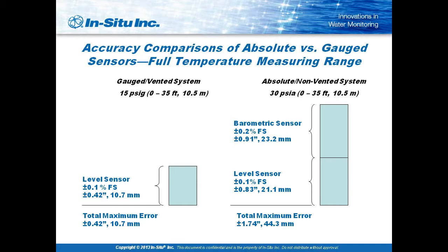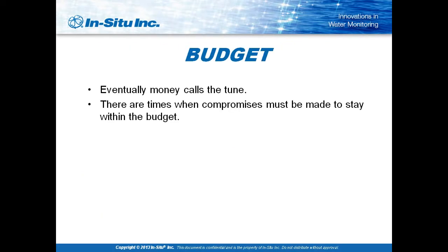But if I'm doing aquifer characterization for an ISR project for uranium, I very well might need it to satisfy my permit. So you have to determine what your accuracy requirements are, and then use this data to determine the sensor that you really want to use.